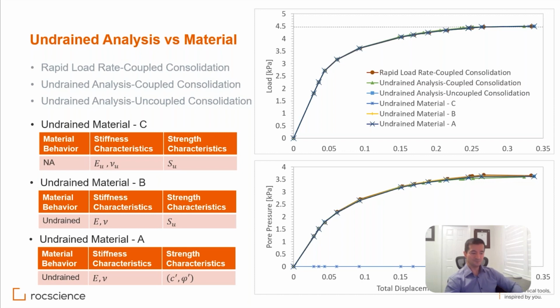Thank you so much. The second question is how to deal with incompressible elements. Okay, so within all this formulation, we have numerical instability, numerical issues with incompressible elements. The way that is handled in RS2 and RS3, within those matrices that we have, for example, that E matrix, we are using a special case of shape function and a special case of integration inside the element, so that we can overcome these kinds of issues.